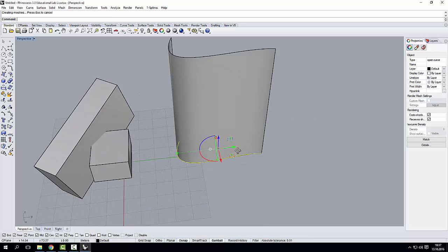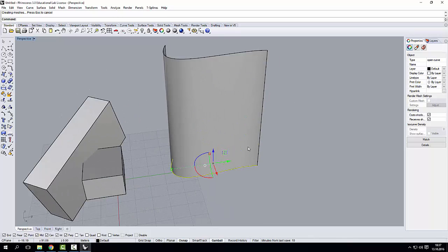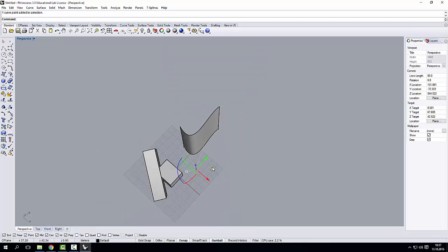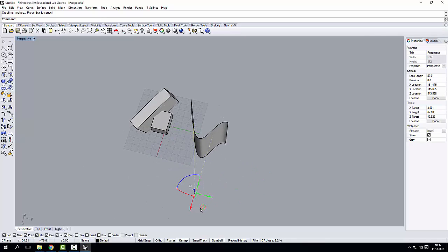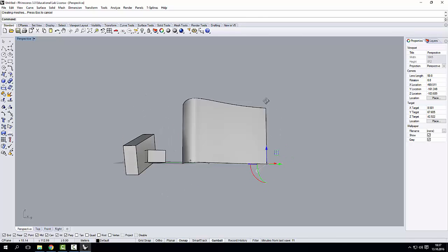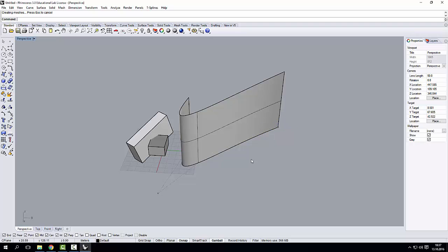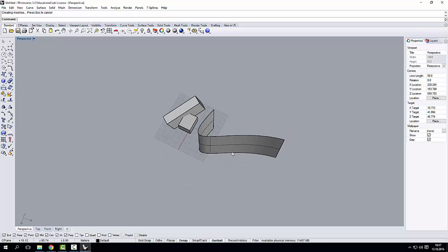Okay, sorry, I got interrupted because F10 stops the recording, but basically what I want to do now that I've recorded the history, if I switch on the points, I can take this geometry, I can move it, and my extrusion will follow. So basically, by controlling the line itself, I can modify the extrusion. Okay, we're going to look at this mode a little bit better later. There's going to be an entire lesson only about this.